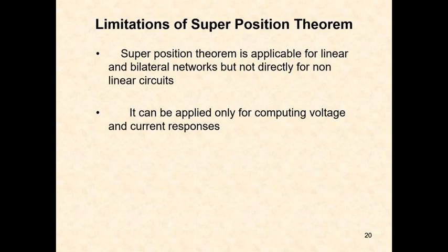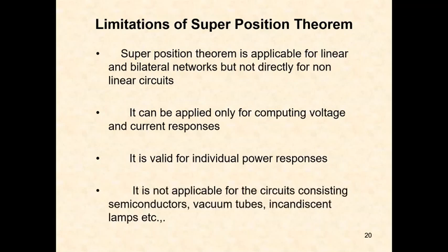It can be applied only for computing voltage and current responses, but not power. It is valid for individual power responses, but not for the supplied power.